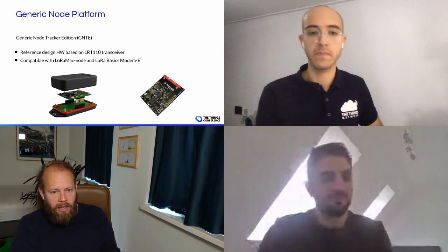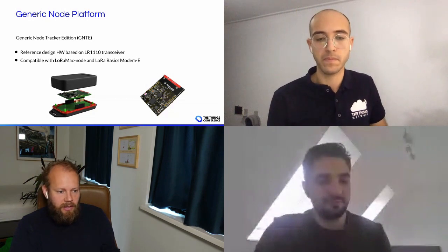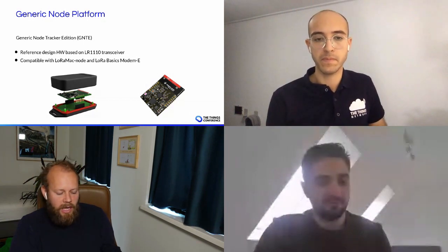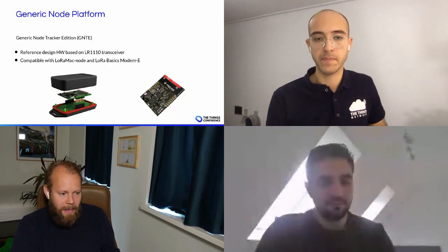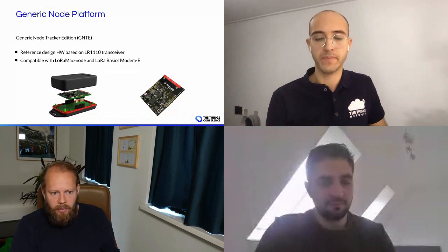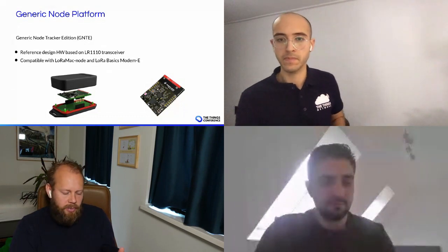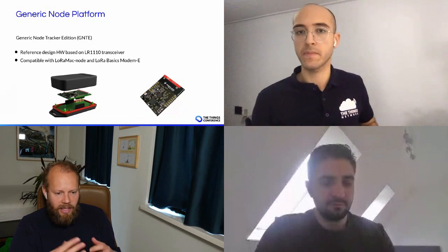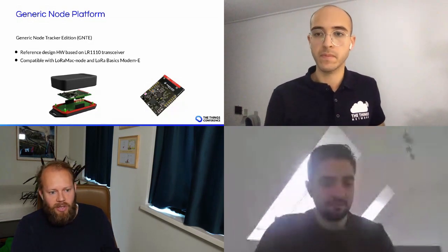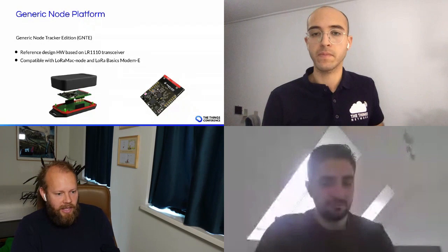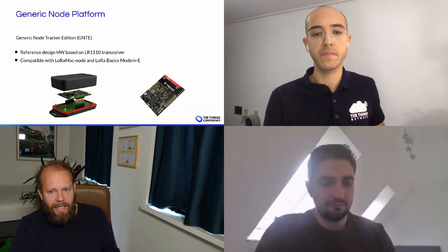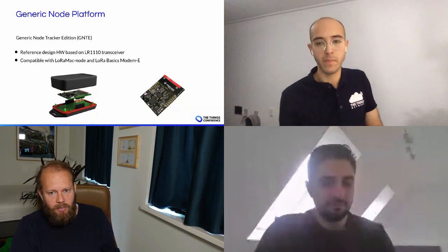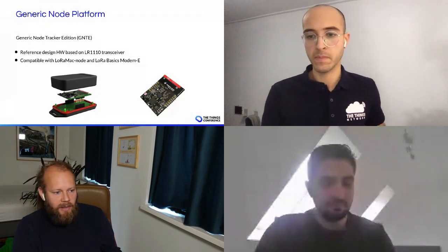that includes using batteries that are part of circular economies, like AA and AAA batteries, because e-waste regulation is coming, and firmware over-the-air update, because 2 weeks ago, the UK government presented a trial legislation around IoT security, and all IoT devices in the years to come need to have firmware over-the-air update and random root keys, and that's why we have the secure element.